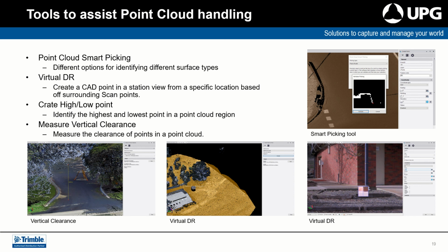This means anytime that you create a point in your project now off scan data, it will open up a tiny little window, and in this particular case we have the face of curb option that is selected, and it creates a little cross section that you can then use to pinpoint the actual spot that you're looking for.